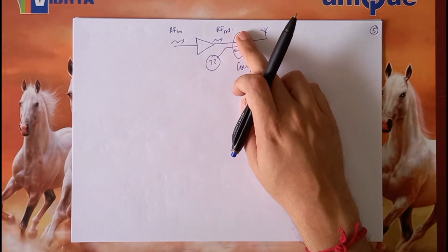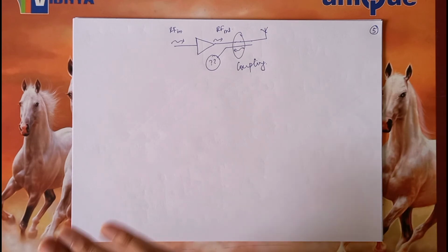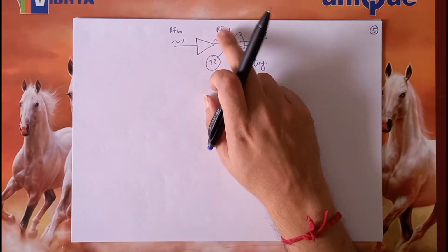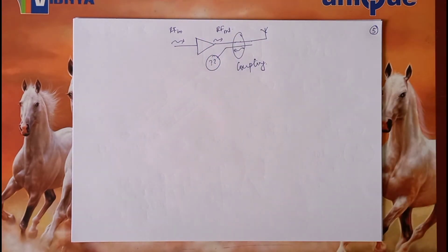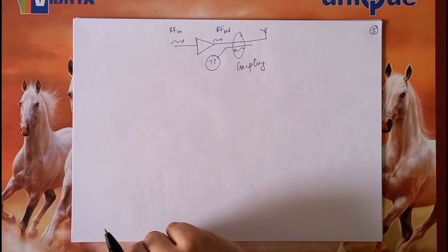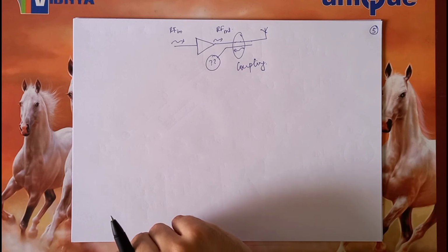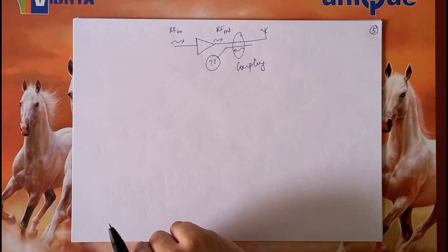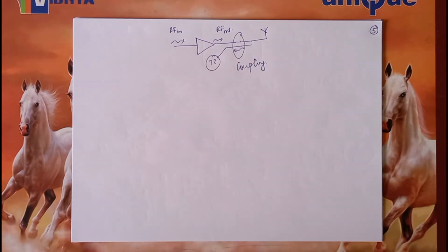And thereby I can say that, okay, using this relationship, I can be satisfied whether the magnitude of the wave in the first conductor is as per our desired requirement or not. So coupling is a very widely used technique to probe the condition of a main transmission line without physically touching it and thereby causing some loading.